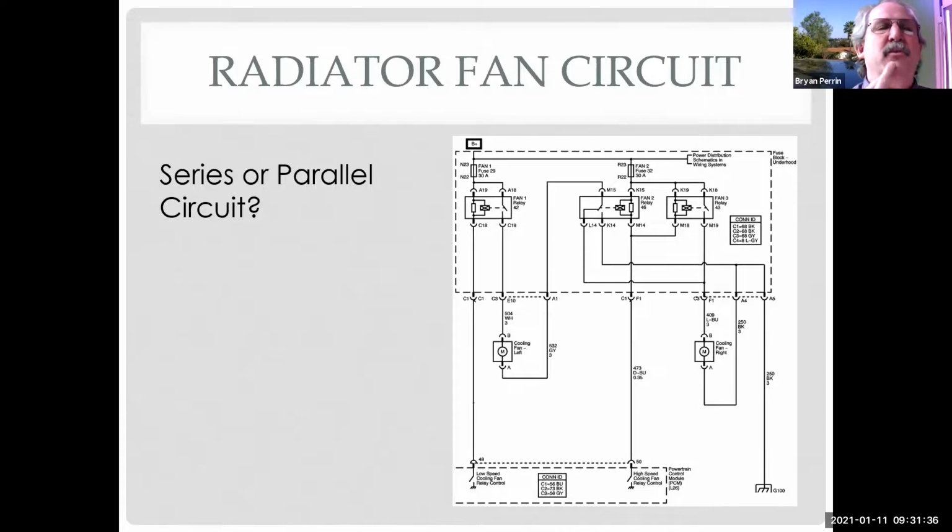I'm going to actually get into relays. We're going to see what they look like inside and spend a little more time on the pins. But we control tons of things with relays. Now, relays can be a 4-pin relay or a 5-pin relay. If it's a 5-pin relay like we have here, I have a leg here that's connected to the default position and a leg here that's connected when the relay is energized. So if I energize the relay, this is connected to K14. If I don't energize the relay, then it's connected to L12.